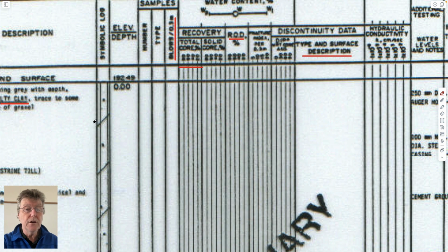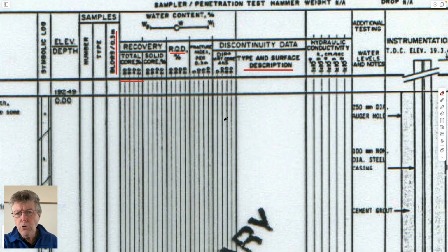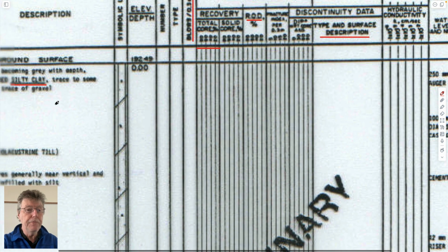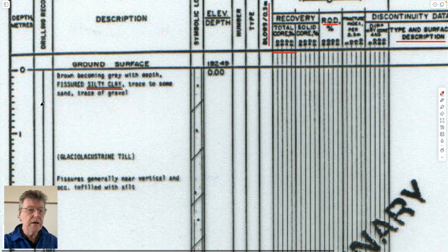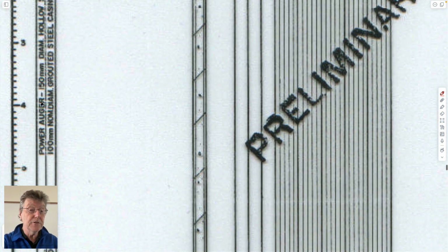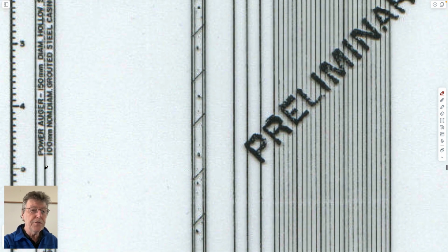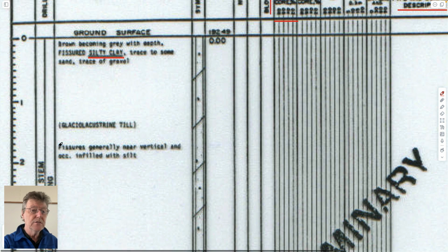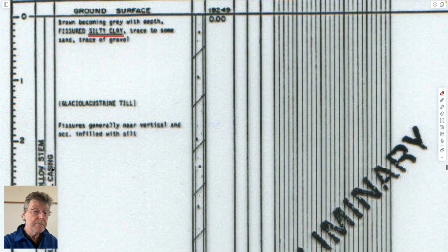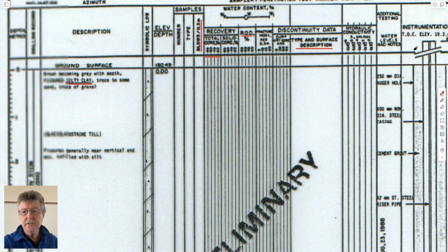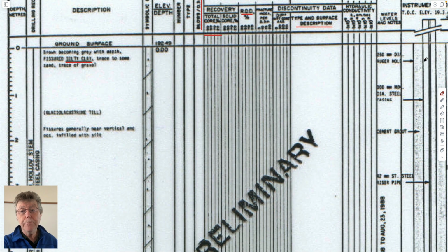And also, once you have these holes, you'd also define what kind of instrumentation you put in. We said before that in drilling this, you go down with a hollow stem auger and transfer to a rotary rig with a tricone to get down to rock. Then once you've got that, you place casing in the hole to stop the soil collapsing on you. The other information that you have is the completion within the hole, which is the right-hand side here. I guess I run out of page, which is saying what happens at each stage.